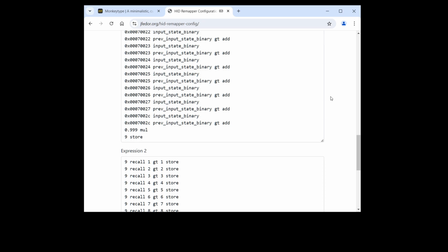Okay, but we don't want this counter to keep building up to infinity. We want it to be some kind of running average of your typing speed. So every frame we multiply it by 0.999. This makes it so that when we stop typing, the value in register 9 will slowly fade back to 0 and all the LEDs will be off. Finally, we put that value back into register 9.